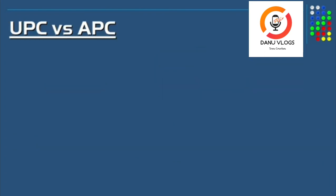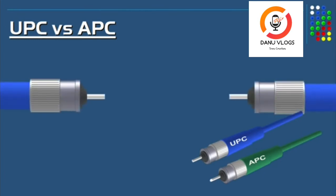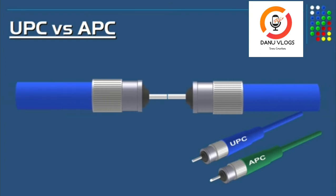So now we're going to talk about the difference between UPC and APC end faces, or tips, on fiber optic connectors. And as examples, we're going to use a group of ST fiber connectors equipped with UPC and APC end faces. Now, when fiber optic connectors make a connection to each other, the point at which the connection is made is not perfect because of the small imperfections of the flat surfaces.